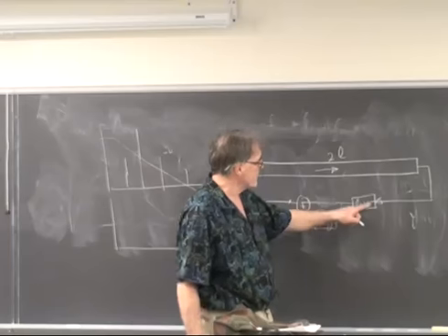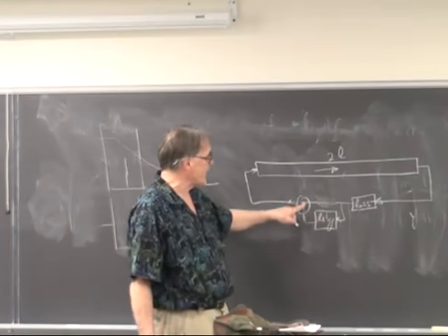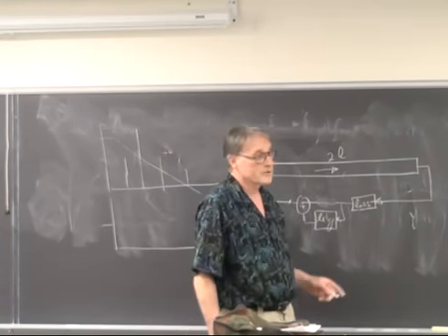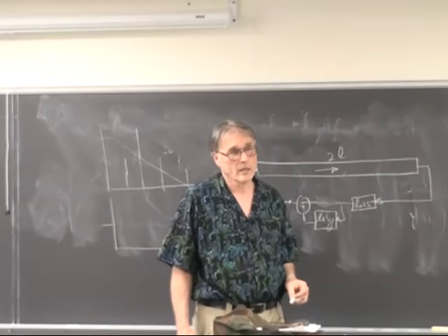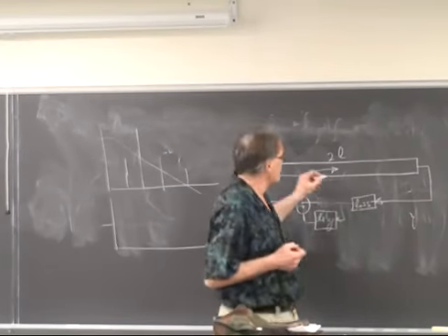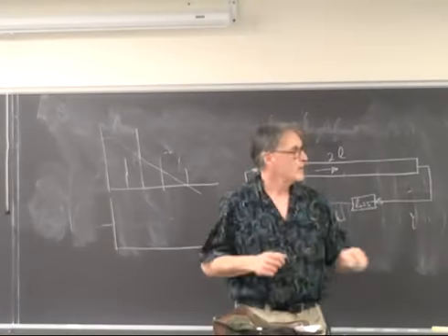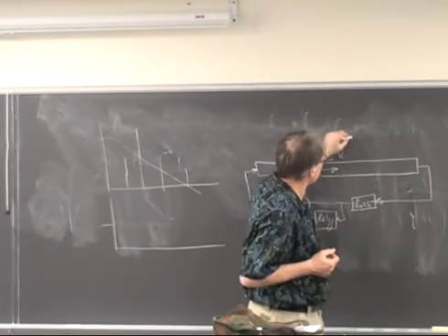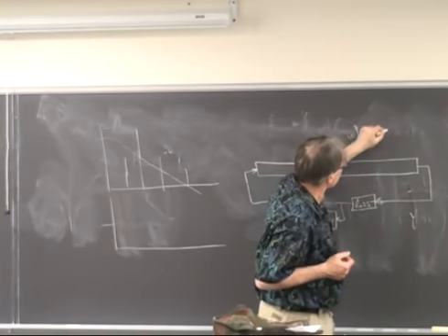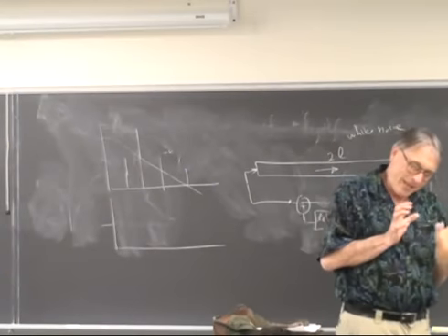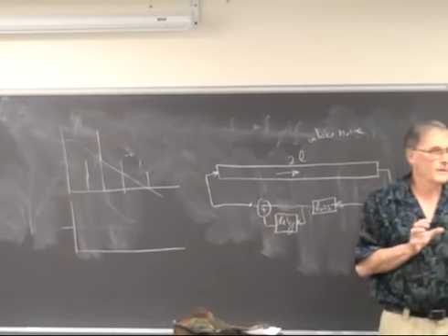It sounds like a plucked string. And so for the cost of a loss element and a delay and an add and a shift by 2 to normalize, you get something that is very string-like. If you load this at t equals 0, at the time you pluck the string, with white noise, you get something that sounds like a fingernail hitting a steel string.